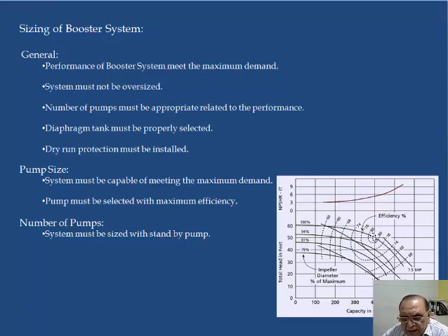And that is exactly what we are talking about. The pump should be selected from manufacturers' curves with the optimum efficiency to save energy. The number of pumps must be sized with standby pumps, so that in case of maintenance and other problems, standby pumps can be used to supply the demand.